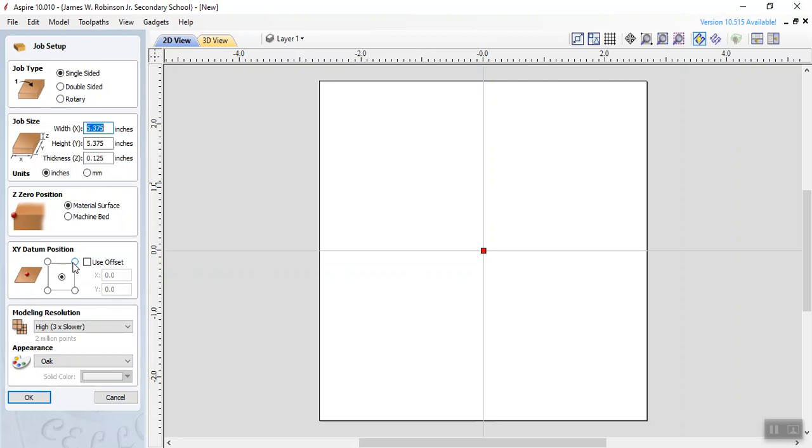Because when you secure the piece of wood on top of the panel, the counter of the CNC machine, you want to find the center first, set the center of the router bit right where it is supposed to be initially, and set the XY zero point. That's the first thing you do, so that's why it has to be established where the center is.